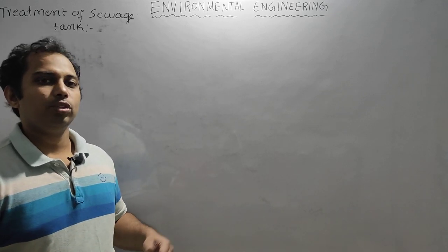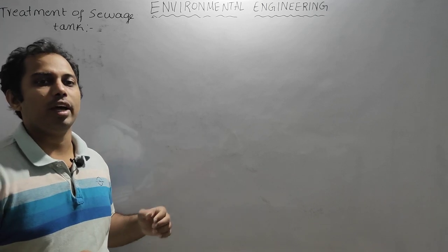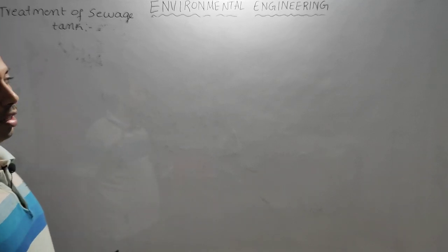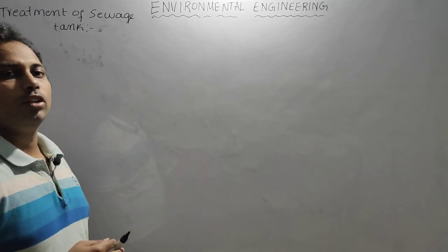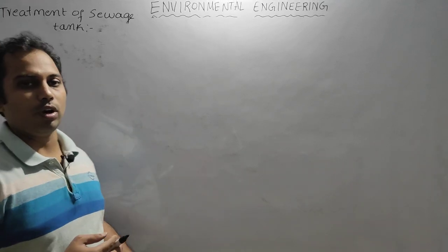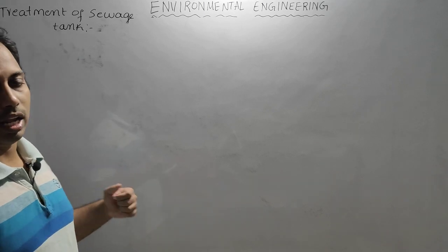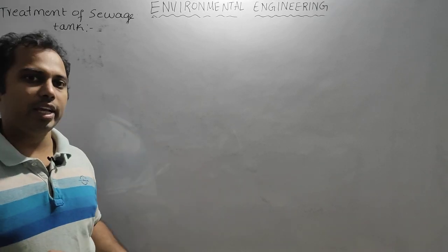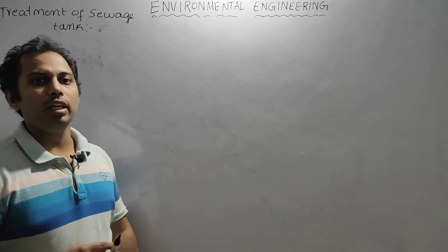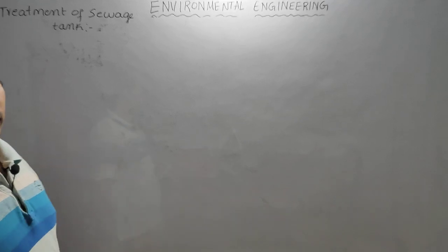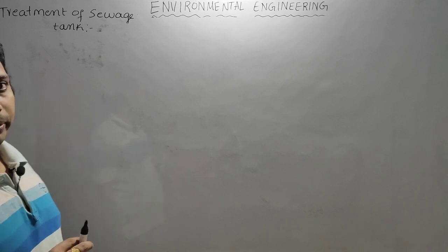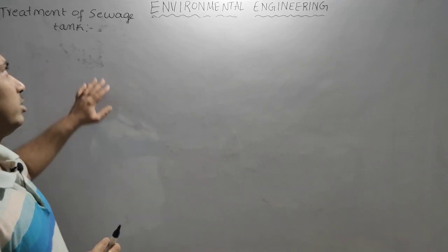That is why the effluent going out of the Imhoff tank will have very low BOD. Whereas in a septic tank, the effluent may contain more BOD, because when sullage water comes, the dry weather flow increases, and this flow will take away the sludge which is undigested.